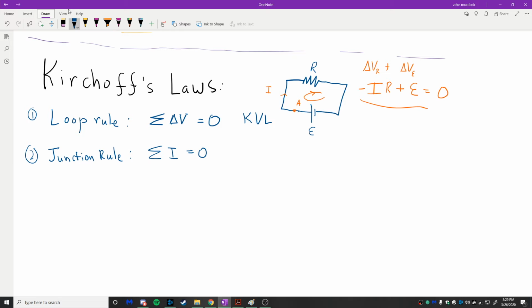A really simple example of this would be like this. Suppose I have a circuit that's like this, and I have a branch in my circuit at some point, and I tell you that the currents flowing in my circuit in this segment are I1, and then here I2, and then here I3. The junction rule states that if I add all of the currents flowing into this junction, they have to sum to 0, okay? So the rule we use is incoming current